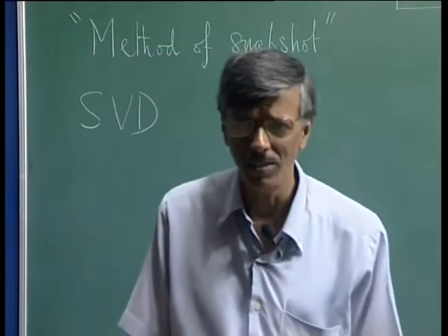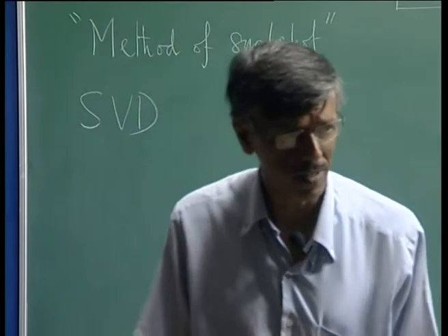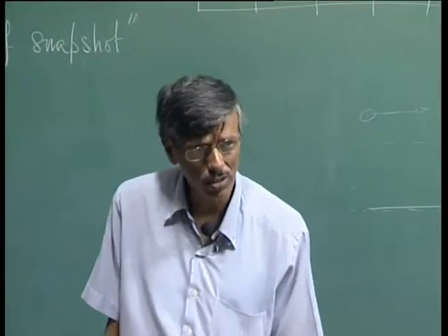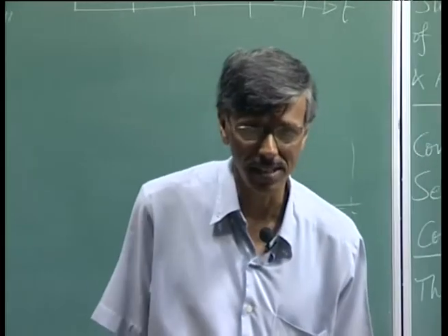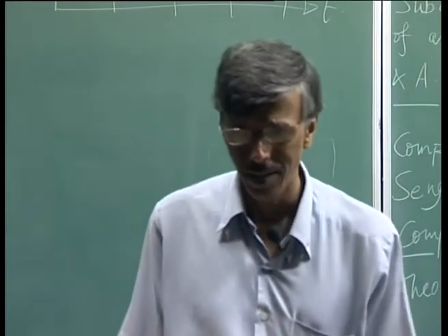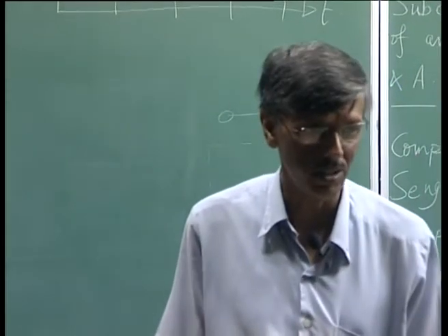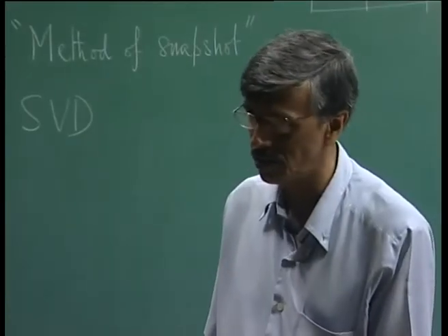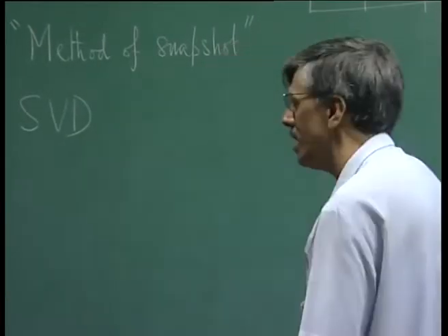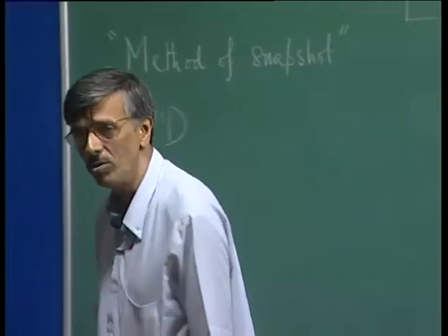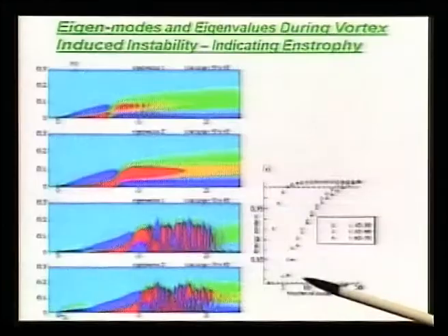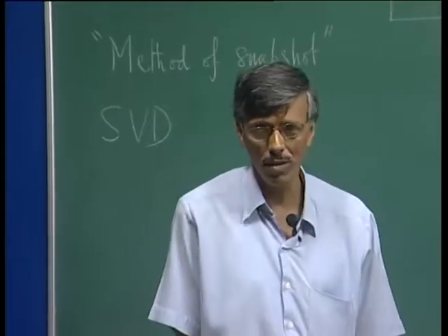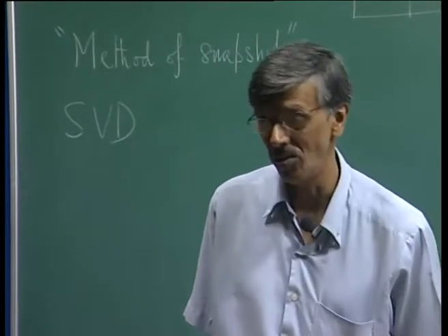You take a real true time dependent flow field, you do the numerical solution, now you do the POD, and you get a glimpse of what is happening. And you understand that this is a fairly decent tool to use. Why? Because you are not making any assumption, you are actually getting the nonlinear solutions and analyzing them. So, basically, accurate solution of Navier-Stokes equation plus its proper orthogonal decomposition hands us down a very powerful technique of studying nonlinear